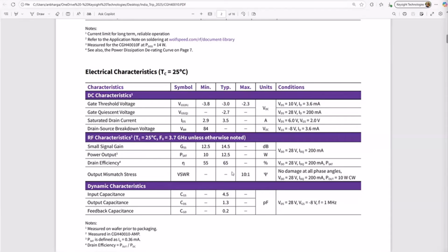Now here, you have to make one distinction. There are two efficiencies which you will hear if you're dealing with PA. One is power added efficiency and another is drain efficiency. Now, if it was a live session, face to face, I would typically ask the attendees, which one do you think is more practical? Should you go behind drain efficiency or power added efficiency? In a typical specification, they simply mention efficiency, but do they mean drain or power added efficiency?